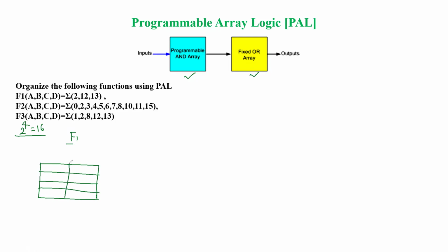So here we have 4 rows and 4 columns. Variables are given as A, B, C, D. Otherwise, if variables are not given, then we can use variables as per our choice. Here we have 00, 01, 11, 10. If you want, we can write in terms of C and D also, like 00 is C dash D dash.